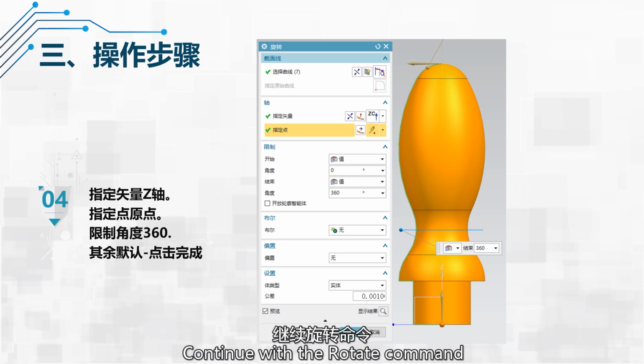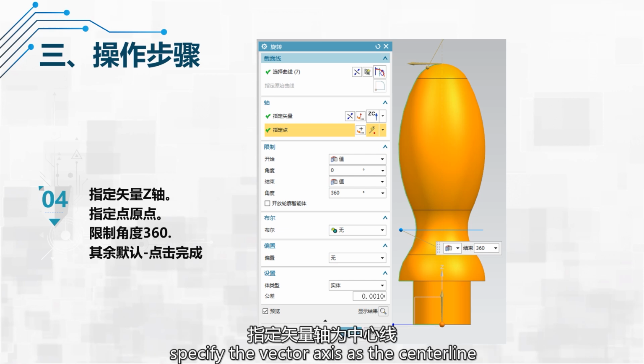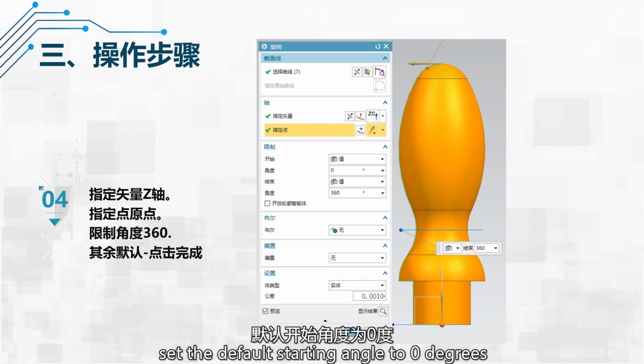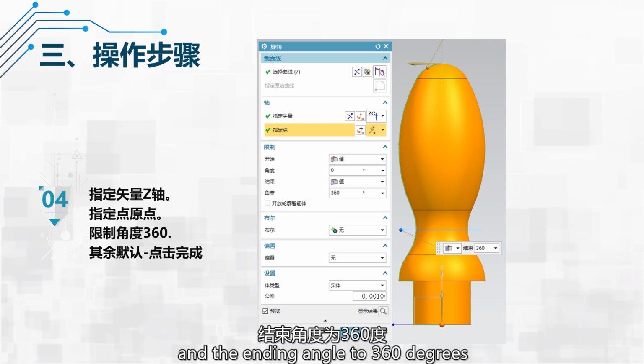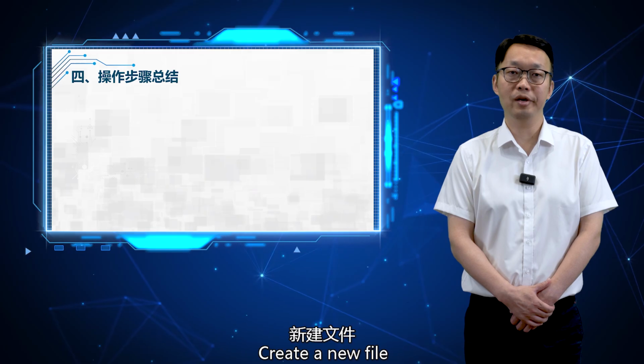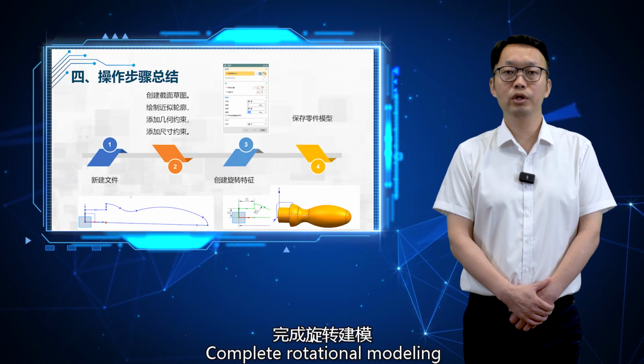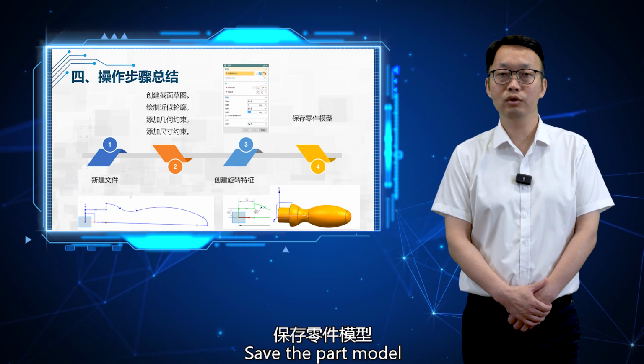Continue with the Rotate command. Select the curve as the sketch curve just drawn. Specify the vector axis as the center line. Set the default starting angle to 0 degrees and the ending angle to 360 degrees. Rotate it once around and click Confirm to complete the handle modeling. Create a new file. Draw the section sketch. Complete rotational modeling. Save the part model.